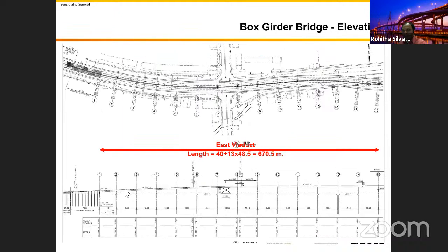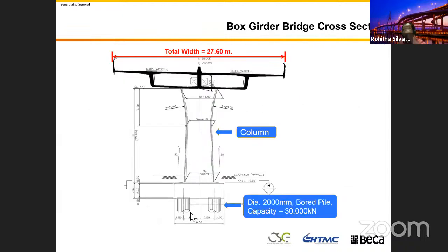So when you are on a bridge, driving a car, you brake, you stop your vehicle, then you accelerate, you get traction and braking, creep, shrinkage and everything. Then this bridge is all the time pulling in and out, right? Thermal behaviors, this bridge is moving. It's moving like a cantilever structure. If you design it with 4 legs in here, this bridge foundation will be acting like a table.